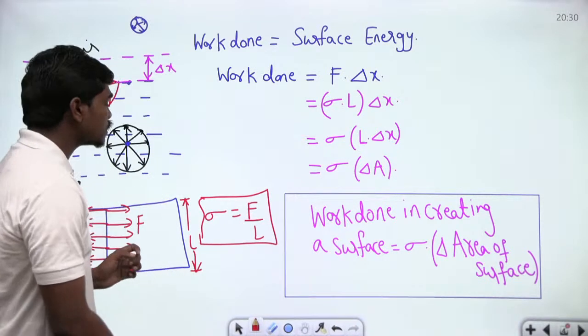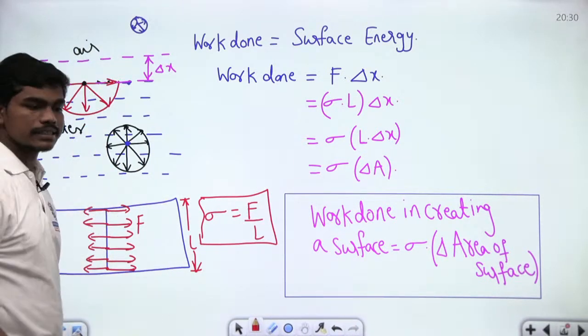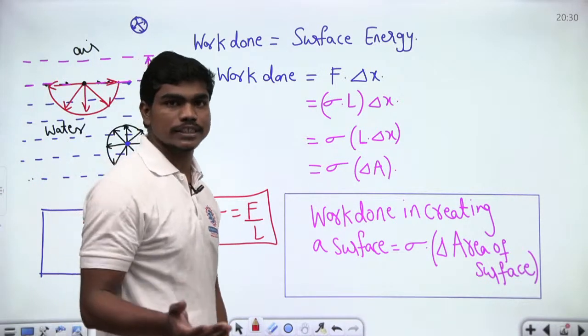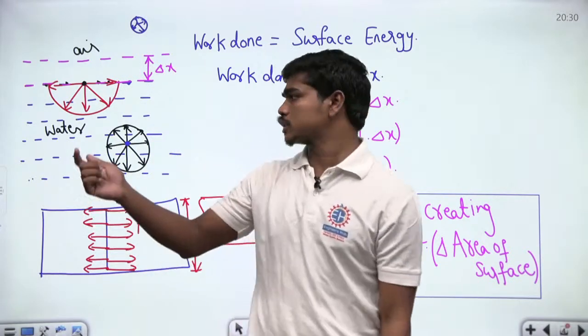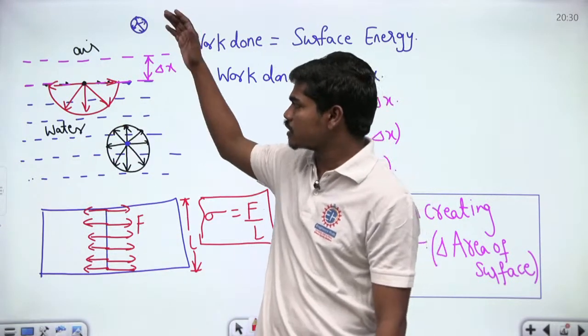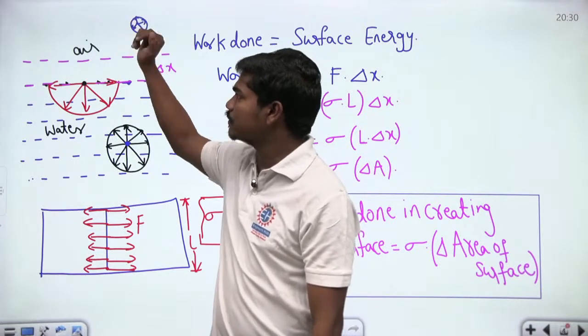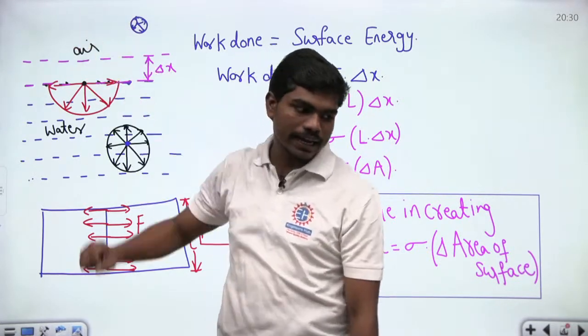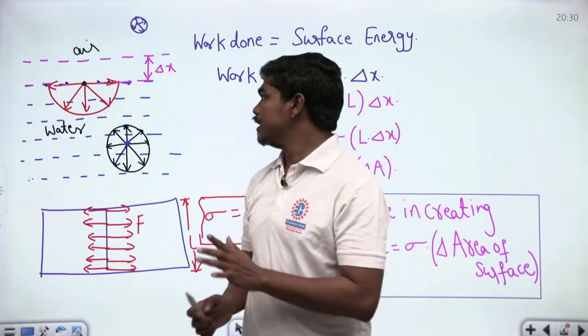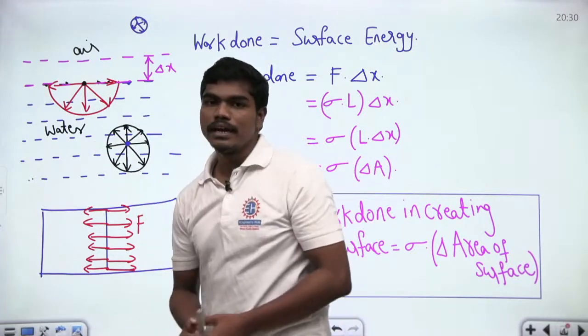Look, why? Because cohesion forces get decreased. Correct? We have seen this in the case of viscosity as well. Both viscosity and surface tension are because of these cohesive forces. But of course, in the case of surface tension, we have the cohesion forces and adhesion forces because of an external fluid as well. Correct? But if you heat the liquid, then what happens?